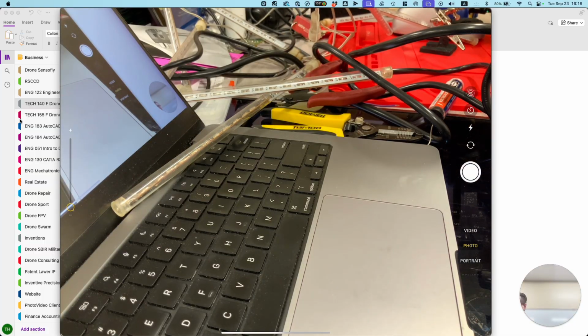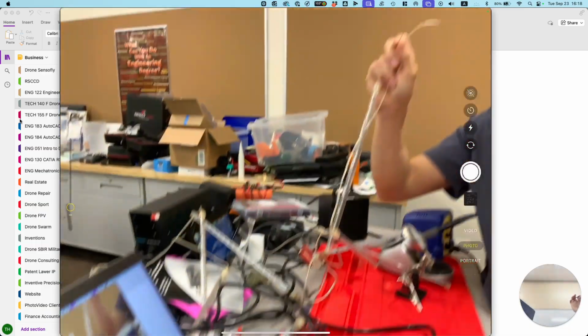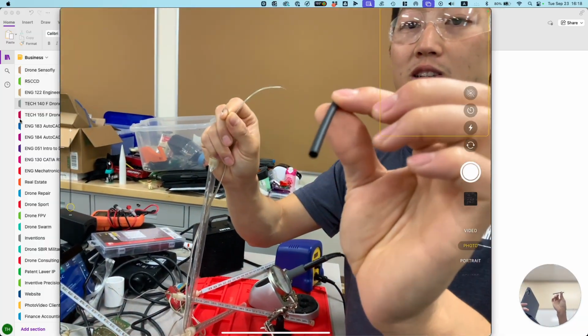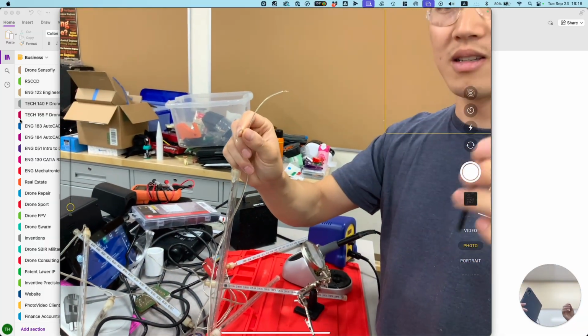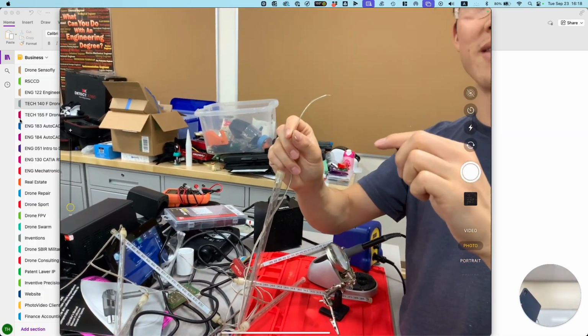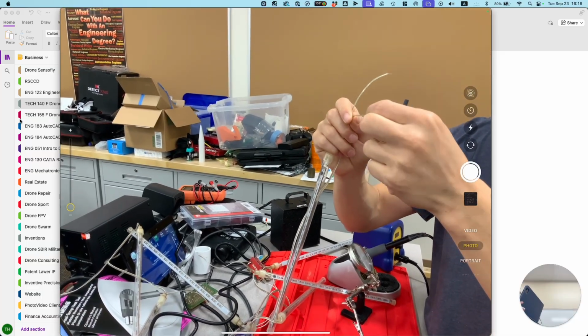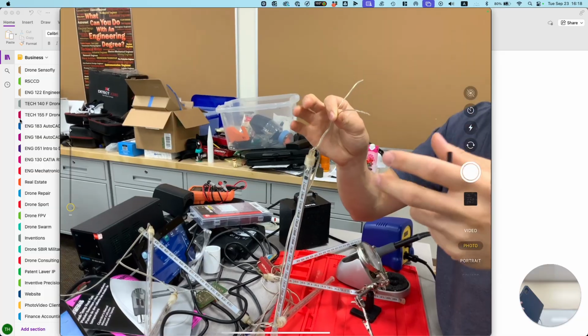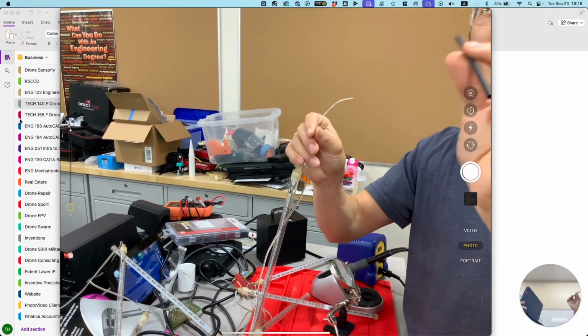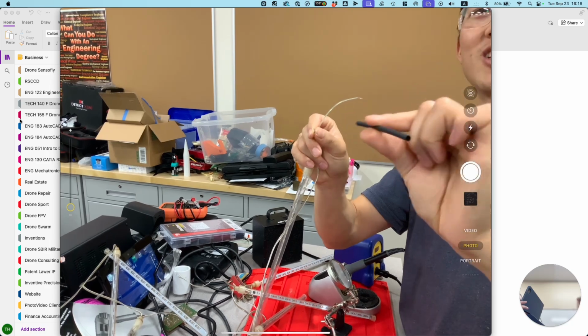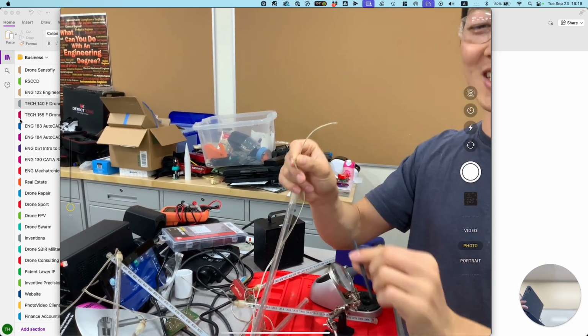So our wire here is maybe a millimeter thick, but I'm choosing a heat shrink that is about 2 millimeters because, as the name implies, it shrinks down. You can choose one that's close to this, but typically our solder joint is going to bulge out a little bit. That's why I wanted to ensure that our heat shrink is going to slip past that point.